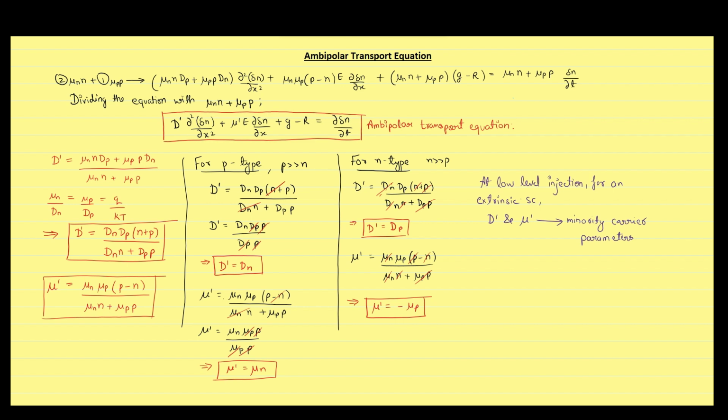Actually, the ambipolar mobility term is associated with carrier drift. Therefore, the sign of the drift term depends on the charge of the particle. So, for an n-type semiconductor, the equivalent ambipolar particle is negatively charged. I have never seen any numerical questions from this concept coming in any competitive exam, and as per me, this is the highest depth from where questions can be framed. But still, it is quite an interesting theoretical point that the excess electrons and holes actually don't move with their respective mobilities and diffusion constants.